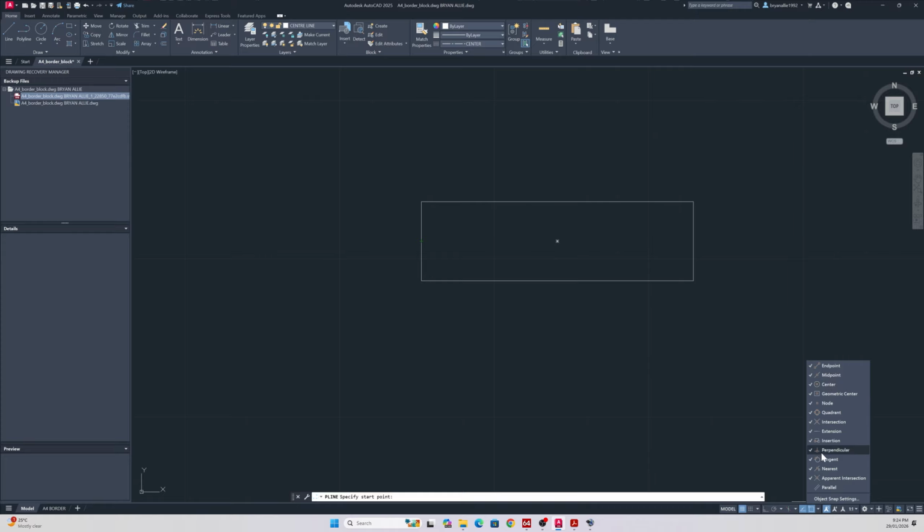intersections, tangent, perpendicular, and endpoint. They're pretty good. The rest, and node. But in this case, I'll hover over the center, go back a bit, where you see the little green dotted line following the cursor. Move out, you see it there. So I just select the point. And if I press F8, put on auto mode.